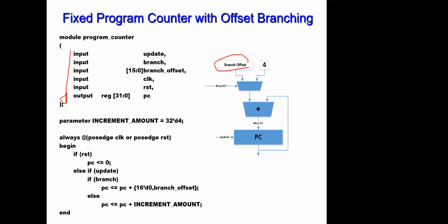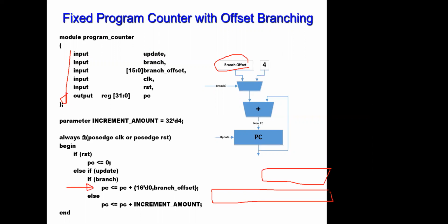The most important step here is this guy, how I can do a sign extension. Sign extension means what? If I have 16 bits and I would like to write this in 32 bits, how can I do the sign extension? As we mentioned earlier, with these 16 bits, I will take that value, correct? Whatever is there.